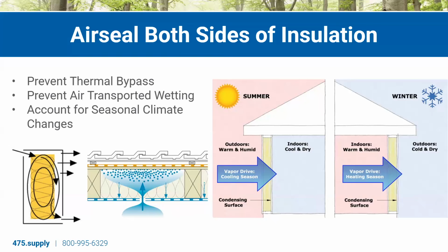And we're in general not really placing a true vapor barrier. We need true vapor barriers below grade. The soil is always wet. That's why we have like a subslab poly membrane. And we would want a true vapor barrier on the top side of a flat roof because you could have water pooling or ponding. But otherwise, we tend to want to dry through diffusion in either direction.